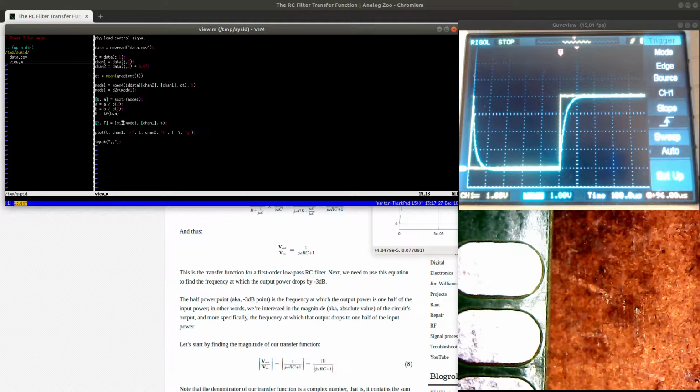If we have a machine and need to do some unit testing, we need to know the model of the machine, but we don't really care about the exact dynamics or what the model means. We just need to supply an input and get an output that is reasonably representative of how the real machine would behave. So we can first identify the model here in Octave, and then transfer this into C code. So let's do that.